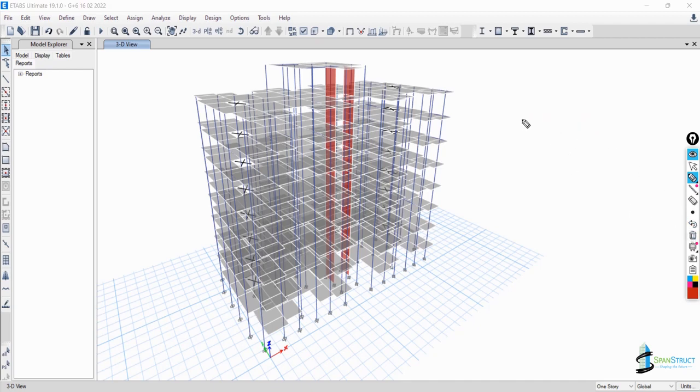When you use a semi-rigid, then this will be SD, semi-rigid diaphragm. It is just a name. You can even use another name like D1 or D2 also. That's not any problem. So D1 will mean rigid diaphragm and D2 will mean a semi-rigid diaphragm.